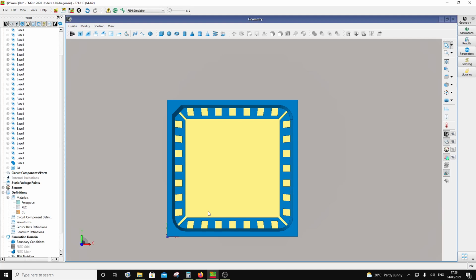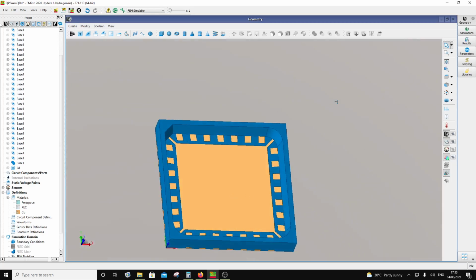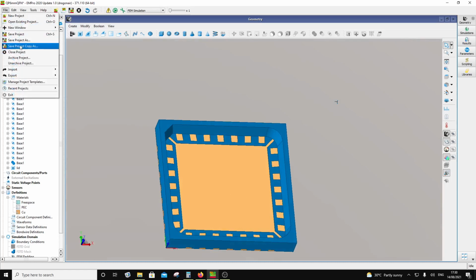If you do a lot of circuit layouts, you will know that, okay, I'll be able to put an LNA and switch in, let's say, 3 millimeter by 3 millimeter. So the pedestal has to be 3 millimeter by 3 millimeter, right? So I have put a 4 millimeter by 4 millimeter, and this QFN is 6 millimeter by 6 millimeter. So I'm just going to save it.